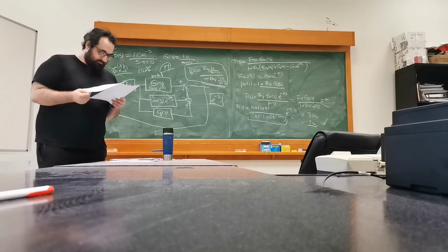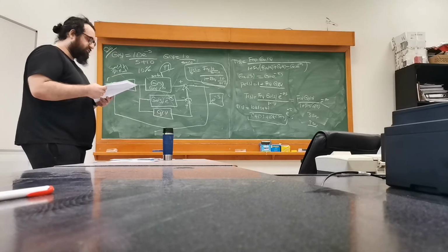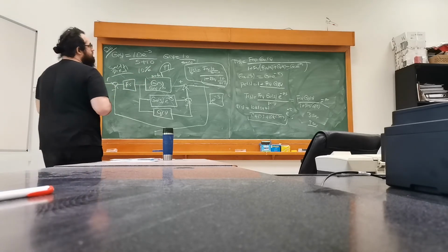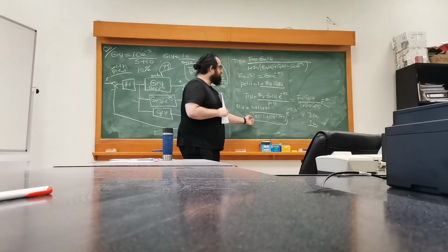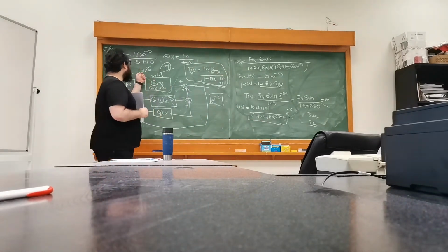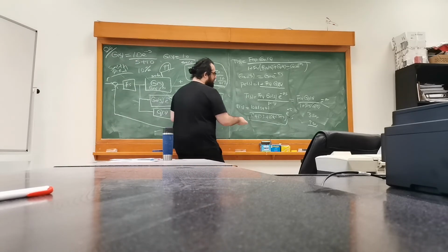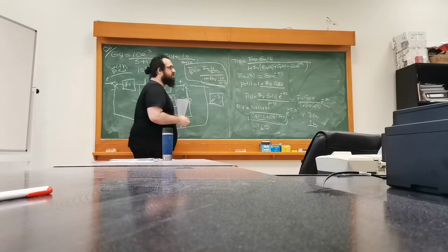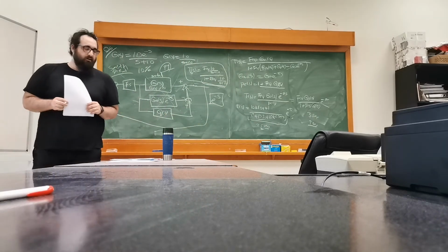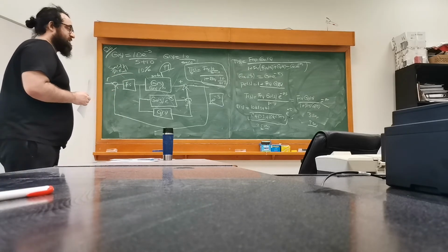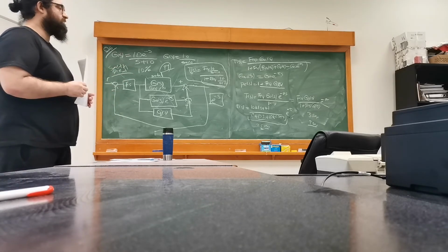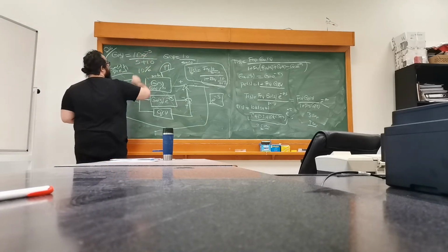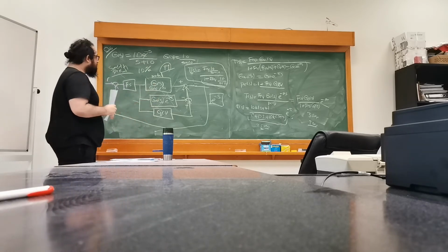Now you can look up the details from the PDF, which I'm going to upload. It's not really about the numerical part of how to design it, because you have the second order system and the zeta value that you want. This part here is 2 times zeta times omega_n. We know what zeta is, so you can work out what omega_n should be, because there will be only that solution. Then you can work out what k is, z is, and so on. Of course, you need a certain dominant factor. But you can get rid of this delay by using the structure, ideally, if it's matching.